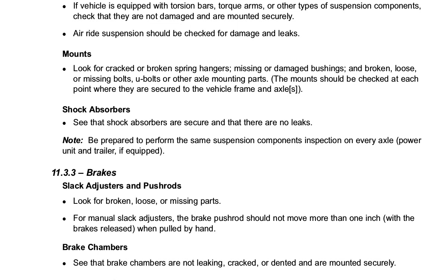Mounts. Look for cracked or broken spring hangers, missing or damaged bushings, and broken, loose, or missing bolts, U-bolts, or other axle mounting parts. The mounts should be checked at each point where they are secured to the vehicle frame and axles. Shock absorbers. See that shock absorbers are secure and that there are no leaks. Note: be prepared to perform the same suspension components inspection on every axle, power unit, and trailer if equipped.